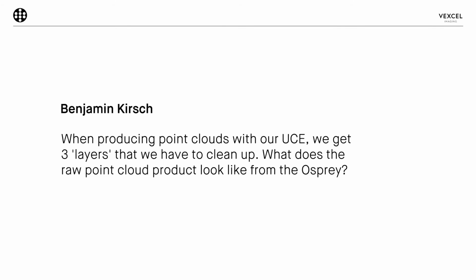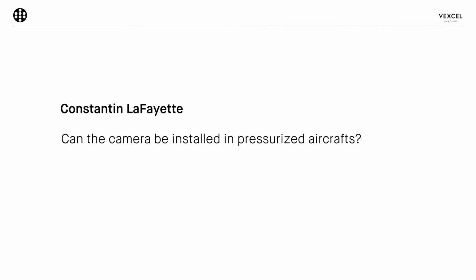Yeah. Thank you, Bernhard. Next question is, can the camera be installed in pressurized aircraft? I would say in general, yes. But as with all oblique sensor systems, this needs to be carefully tested because we also have oblique sensors which are tilted. The impact of the glass on the accuracy, especially of the obliques, is higher than in a purely nadir camera. So the answer is yes, but we should test it to avoid reflections or inaccuracy in the geometry.